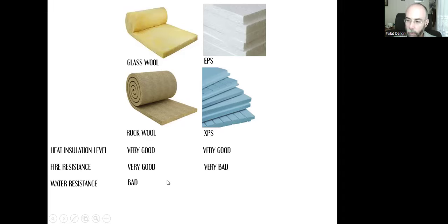They will be filled with water. They will get very heavy and they will lose all heat insulation properties. And these are good, no gaps, no water damage. Pressure resistance, again, these are bad. You can easily squeeze them, crush them. These are better than glass wool and rock wool.